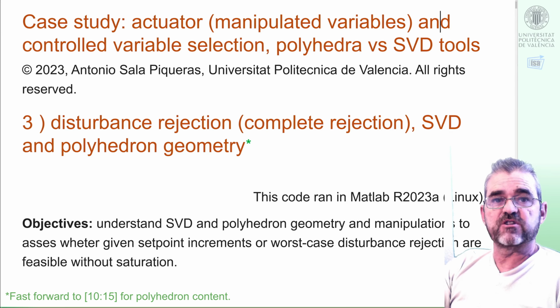And then regarding output scaling, intuitively, if we want the output to be 0 when a disturbance is cancelled by my control system, then speaking about output scaling is nonsense. And indeed, whatever the output scaling we use for our scaled gain matrices, the results will be the same. So EU is important, but not so EY.